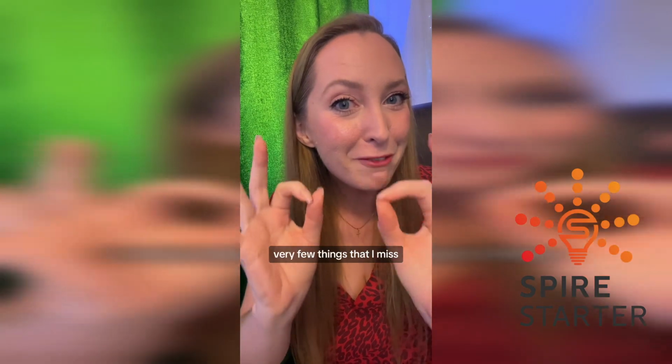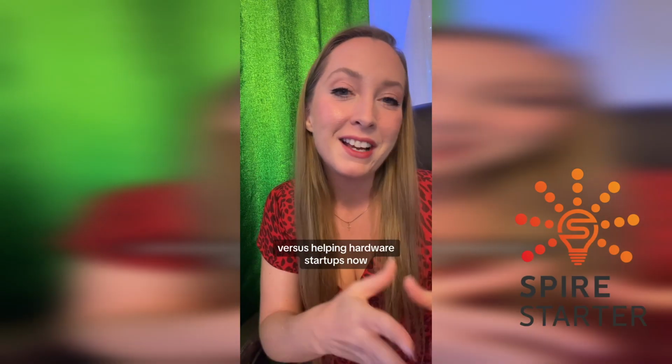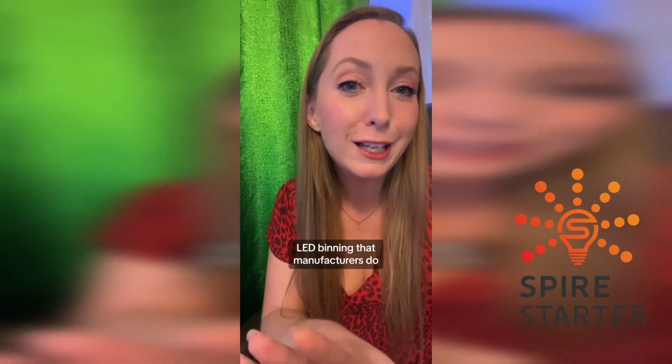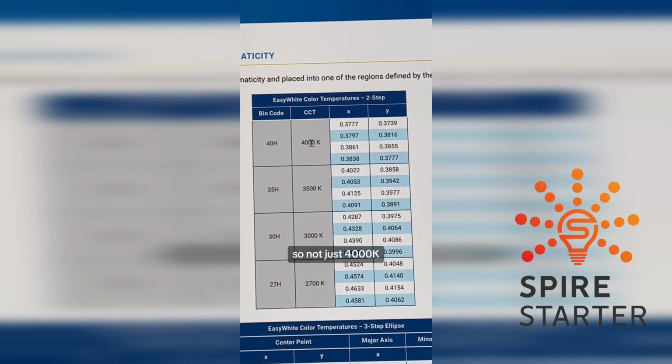It's one of the very, very few things that I miss about working for larger manufacturers of luminaires versus helping hardware startups now independently. Now, flux is not the only LED binning that manufacturers do. Manufacturers also sort by chromaticity, which is the exact color characteristics on a plot of where these things fall. So not just 4000K, but more specific than that in X and Y.